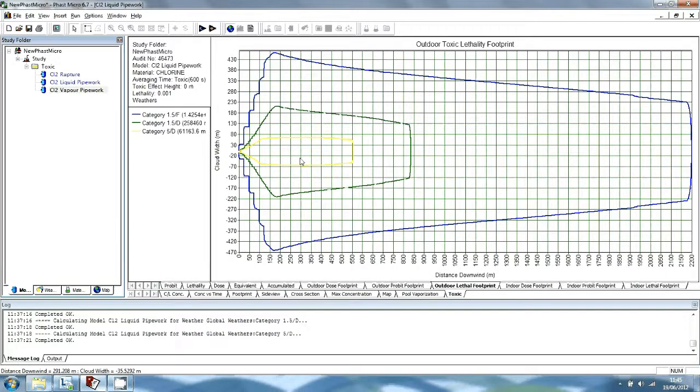We will now define 3 flammable releases. There's a propane sphere at the far north of the site. The propane sphere is the same dimensions as the chlorine sphere and the same design of pipework, and is also operating under saturation conditions at atmospheric temperature. And we will now set the input data for the models.